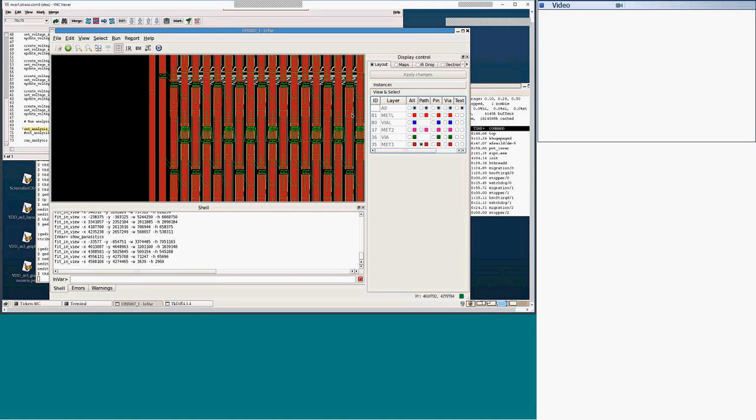But I mean, our approach will work, right? If we just segregate this single multi-finger power device and run the extraction of unreduced DSPF. Yes, this is the recommended way. Okay.